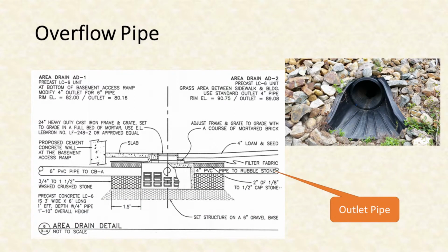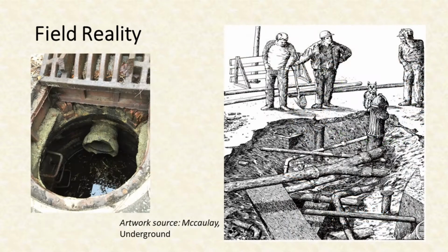Stormwater treatment systems that are sized to treat a certain volume of rain may not have enough capacity to treat the entire stormwater catchment during all storm events. Most have an overflow pipe to drain the system when it's overwhelmed. That drain pipe becomes the discharge point for that storm drain system and catchment.